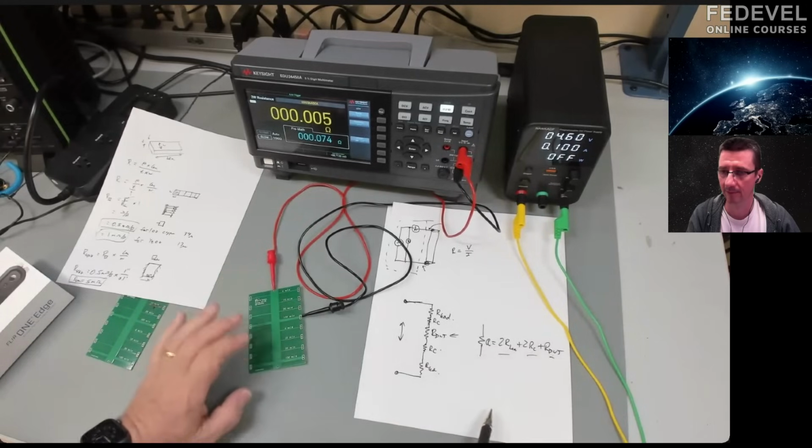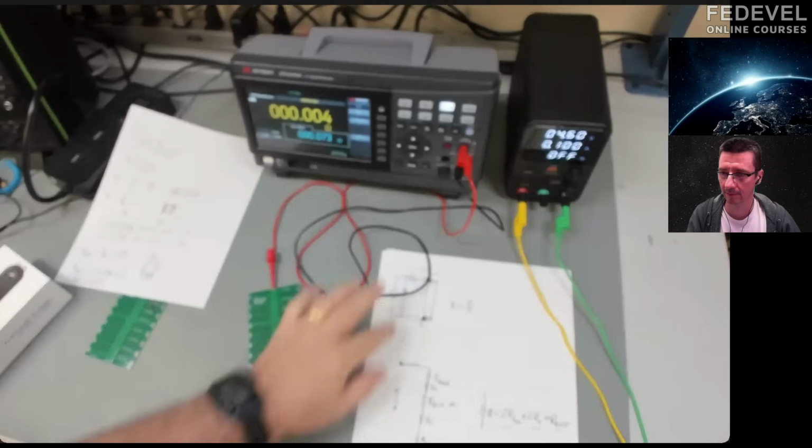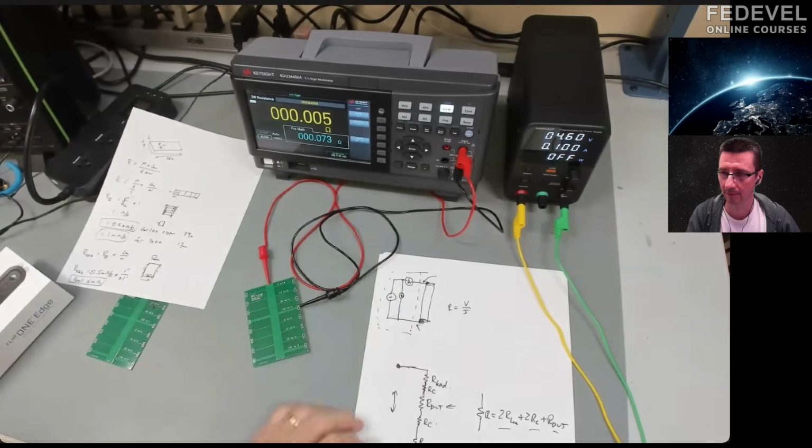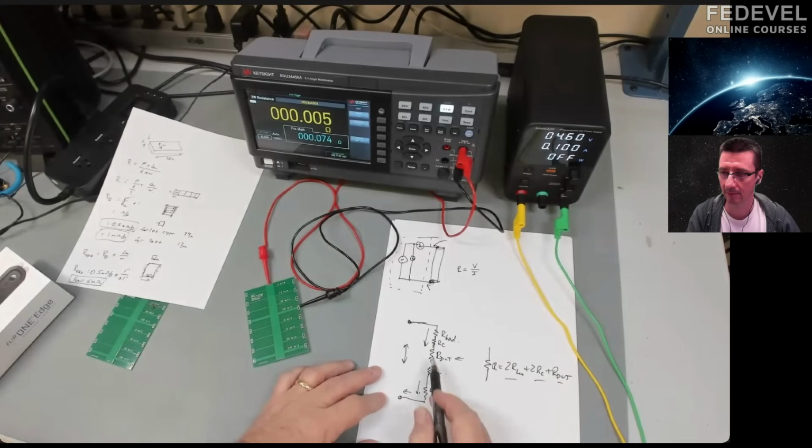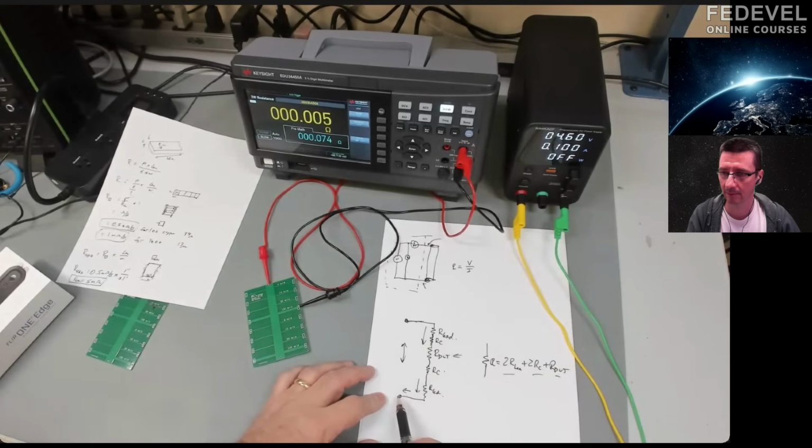And in our example here, the resistance of the thing I care about is a tiny fraction of these resistances. And so the technique we're going to use is we're going to separate out the voltage and the current measurement. We're going to still force current through the whole thing. And of course, they're in series. So every element in series has the same current going through it.